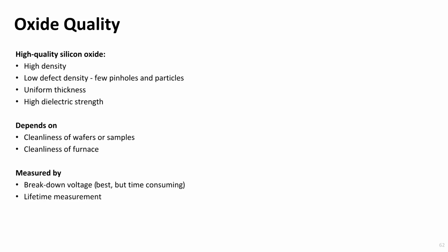The oxide quality can be estimated by measuring the breakdown voltage. It is a destructive and time-consuming test that requires dedicated test samples to be made, and the measurement tool belongs to DTU HealthTech. It is also possible to measure the lifetime of the silicon oxide. We will not go into details about breakdown voltage and lifetime measurements in this presentation.